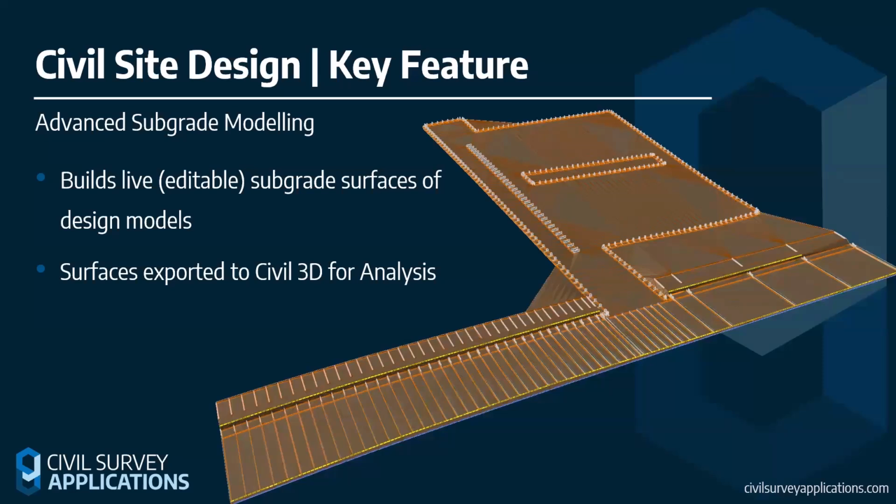In the theme of visualization, we've also got Subgrade Modelling. Really, really good piece of kit this, because this is essentially going to give you a surface of the underside of your design, essentially giving you a surface through any materials you have specified on your strings and generating that for you for the purposes of, say, bulk earthworks. And obviously, crucially, with any of what we're doing here, we can pass this over to Civil 3D.